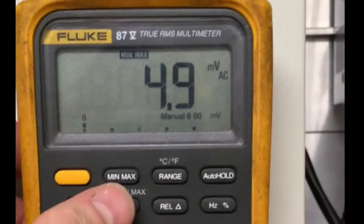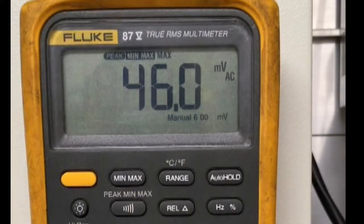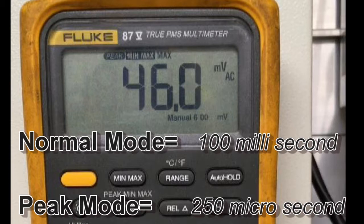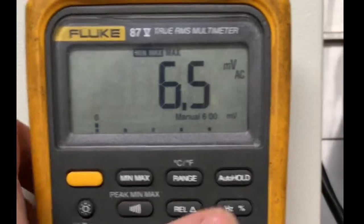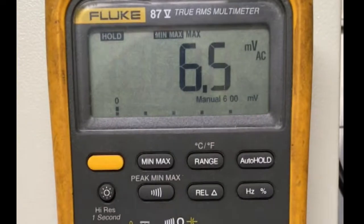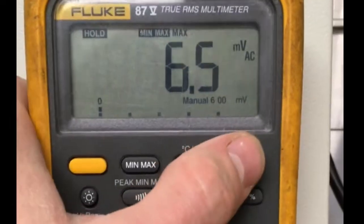Pressing the tone button while this mode is active changes the response time of the measurement from 100 milliseconds to 250 microseconds. This will be indicated by a prompt of peak on the display screen. If you wish to stop recording momentarily, press the auto hold button. When you are ready to record again, press the auto hold button again.